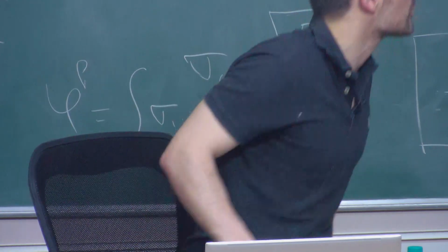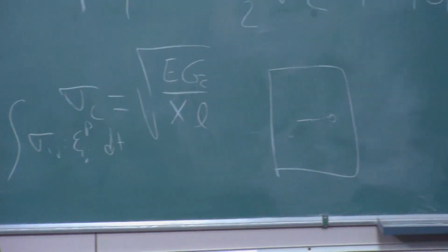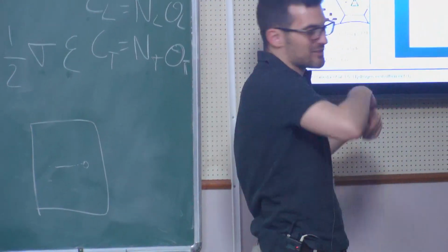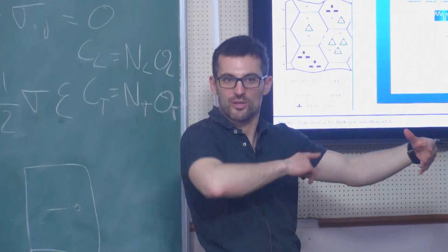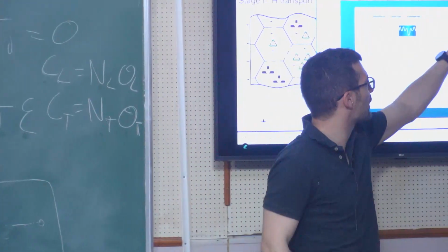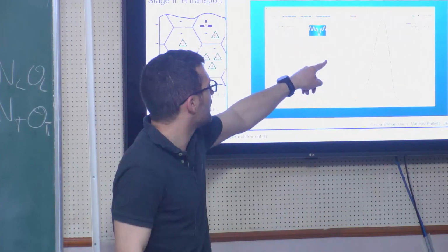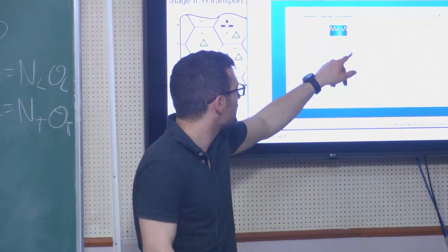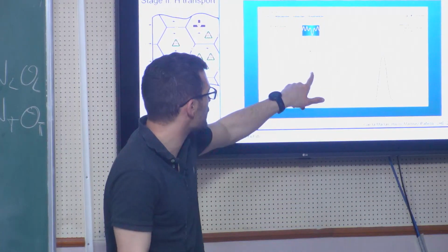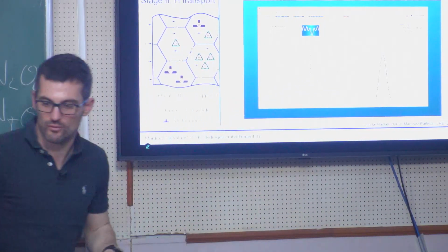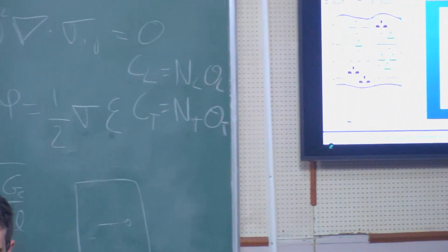You can see that it has a place where you can put the simulation data, so you can pick the models: Oriani, McNabb-Foster, no traps. You put the graphical output, and in seconds, since this is a 1D finite element simulation, it runs quite fast, you get the desorption rate versus temperature for the different models. You can plot hydrogen in the lattice, hydrogen in traps, or the combination of both. You can change the units of those things.